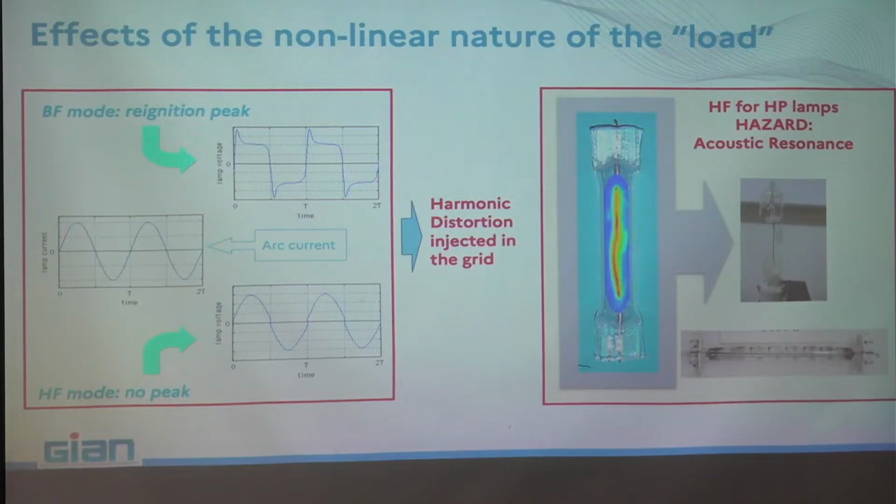That means what? If you overheat the lamp and the form of the lamp is distorted, then the frequencies may drift, or if you do dimming of the lamp, then the frequencies will drift again. And that means simply if you use a high frequency power supply, say above a few kilohertz, then you make dimming, or I don't know what else, always you can be sure that you will have acoustic resonance phenomenon, and this is very bad for the lamp.